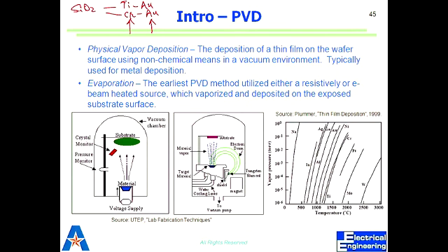A thermal evaporator is an example of that, right? The thing that we deposit metal on. Is thermal evaporator considered PVD? Yeah, it's just the physical definition. So thermal or E-beam, the only difference is how you are melting your source.